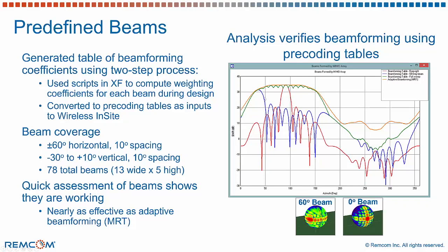And that's plotted above in the horizontal plane in blue. When we combine all of the beams in the table over a horizontal sweep, we get the plot that's shown in green. And we can see the peaks of each of the individual beams as we were creating this plot. What this green plot represents is what different CPEs or different receivers in any direction could receive when they determine the maximum beam and then use that beam for the downlink communication.